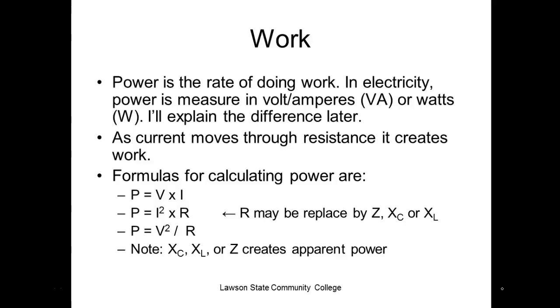So here are our power formulas, which y'all didn't get to in the intro to engineering. The main power formula is where the other power formulas came from. Ohm's law has three formulas that we solve for different things. The main one is voltage is equal to I times R. And then we can put that in a wheel or a triangle, where we put V at the top, and then we put I and R here.